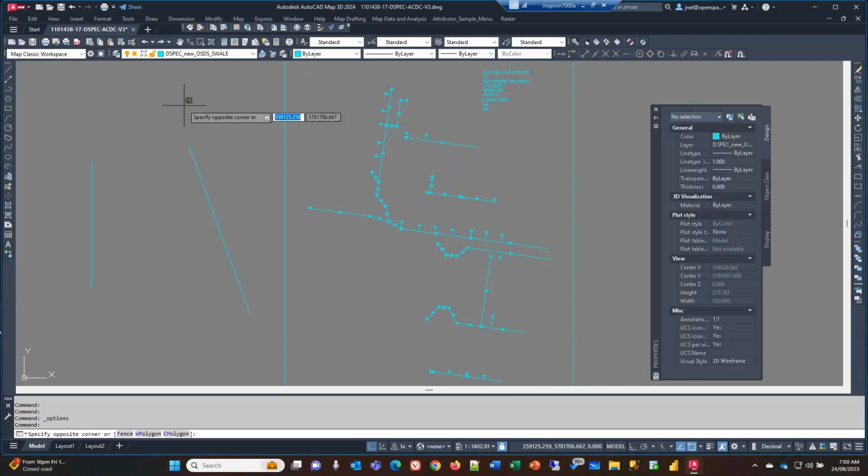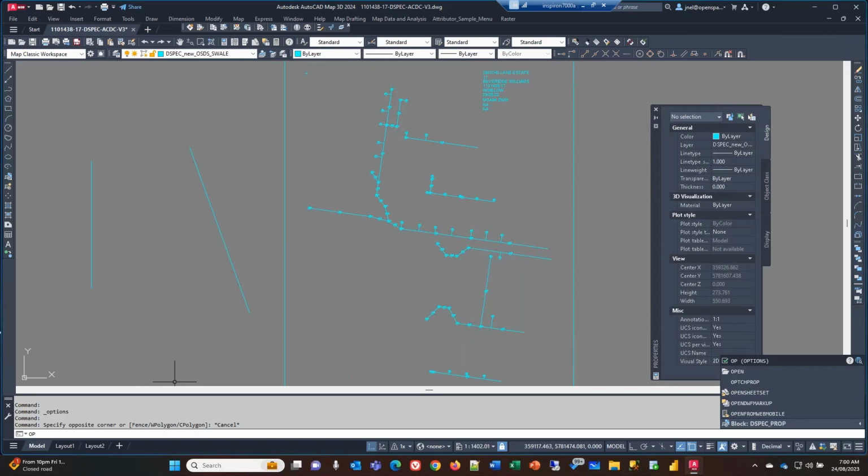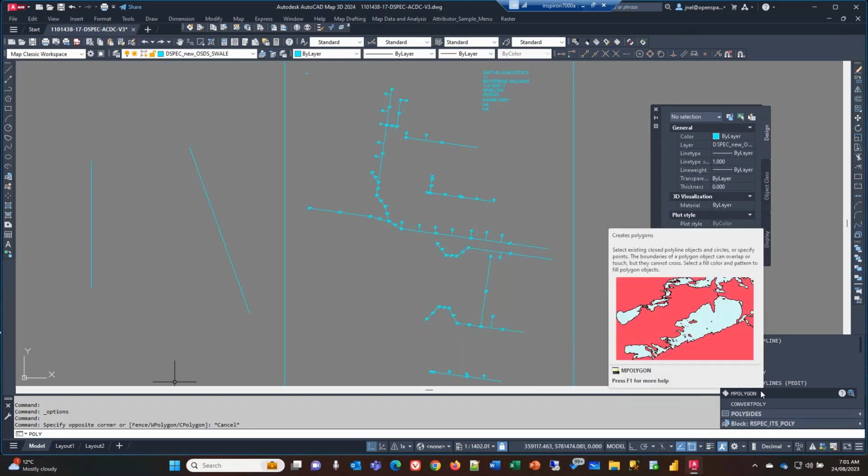Now, if I type anything, it will start from all the commands within AutoCAD and give you possibilities. If I type and make a mistake, it will still filter based on that information to say, okay, what is it that you may want to do? So you can easily pick any particular tool that you want. Once again, it will then give you some more help on that.